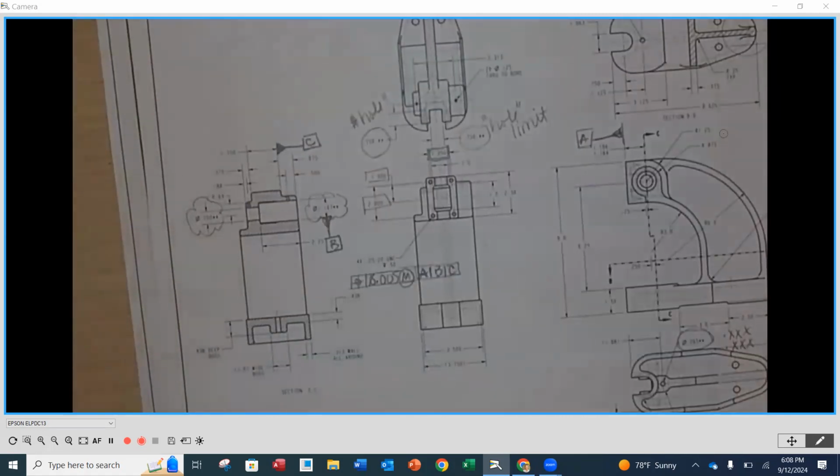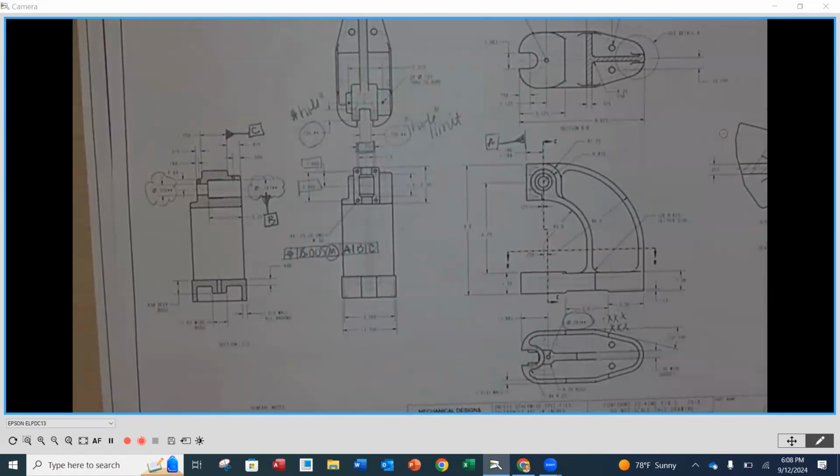And that's as far as the GD&T I'm going to be really worried about. I wanted you to apply some positional tolerances, this fixed and floating, we use the fixed, and then also converting the dimensions there for those features of size. You could add it in more places if you want, but I just wanted to line those two up and ease into it a little bit for you and create a little bit of a review, not go crazy. Because I would rather you understand the couple of places here as opposed to getting overwhelmed with putting it in too many places. Does that make sense?